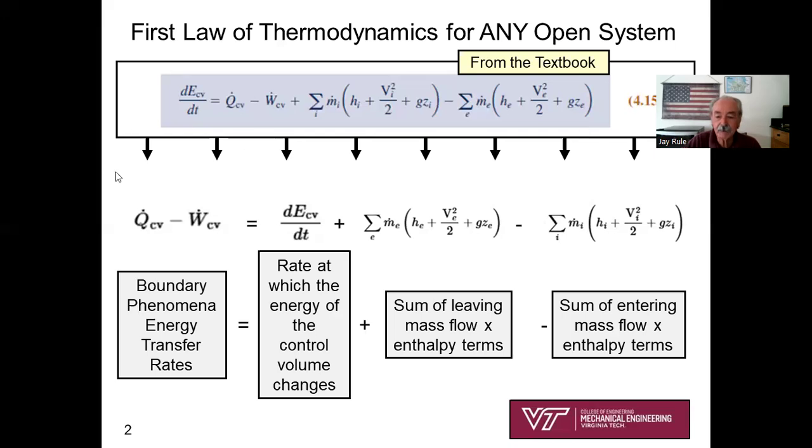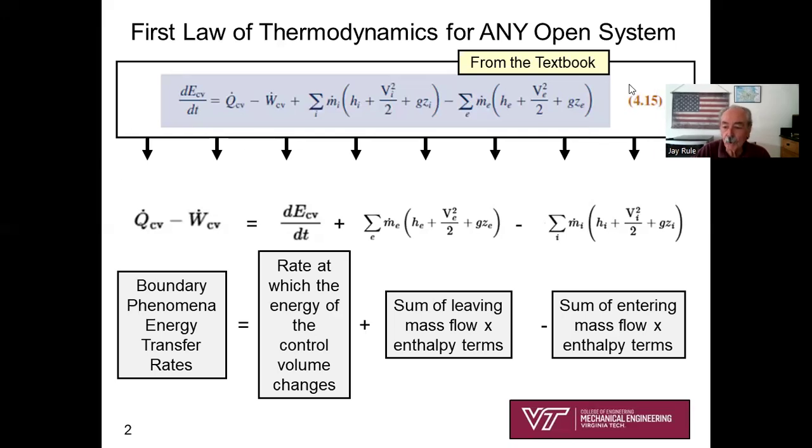Picking up from last time, you remember that there was equation 4.15 in the book, and that was the general statement of the first law for any open system, at any time, with things changing in time. Things are different at lunchtime than they were at breakfast time. Things are all over the map. And then what I wanted to suggest was that you change your thinking, change the way you look at this equation 4.15.